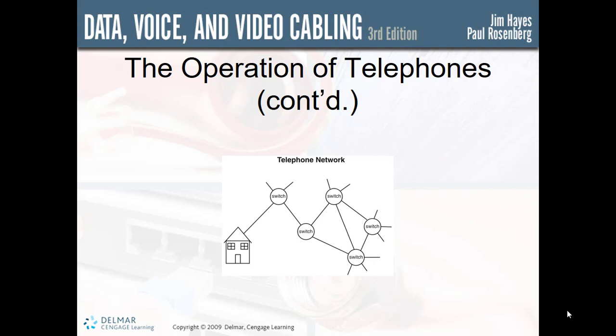Telephone cabling can be a simple four-wire cable inside the home, but four-pair unshielded twisted pair cables are typically used inside an office and are now required by FCC regulations inside the home. The subscriber loop connections to local switches have been on multi-pair wires with up to 4,200 pairs per cable. Most of these large pair count cables have been replaced by fiber optics because those 4,200 pairs of copper wires can be replaced easily by a pair of single-mode optical fibers. All fibers used in telephone networks are single-mode types.